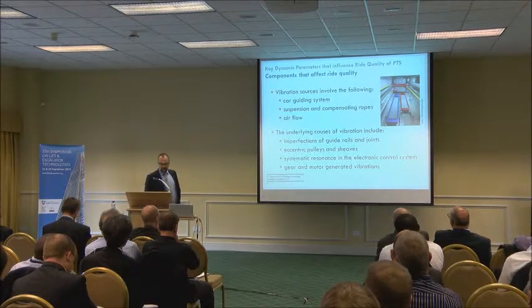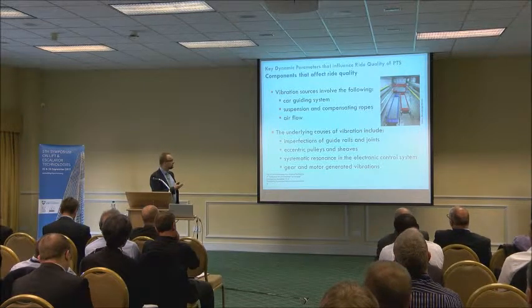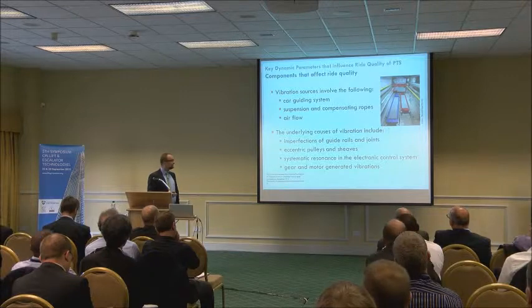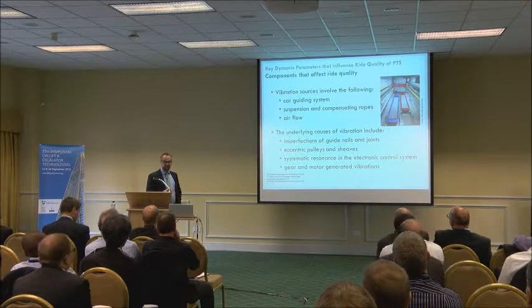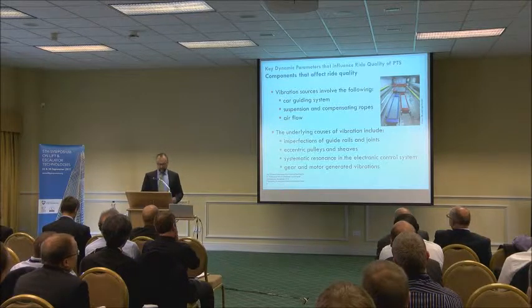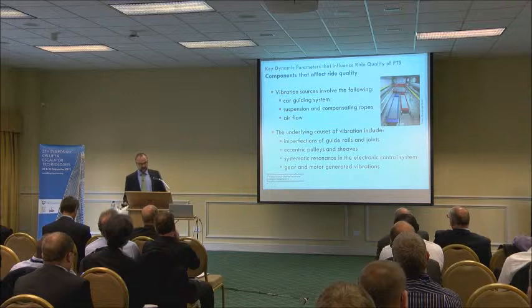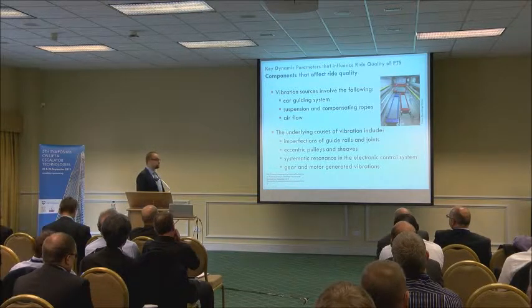The underlying causes of vibration vary, and they include imperfection of guide rail and joints, eccentric pulleys and sheaves, systematic resonance in the electronic control system, and of course gear and motor generated vibrations.